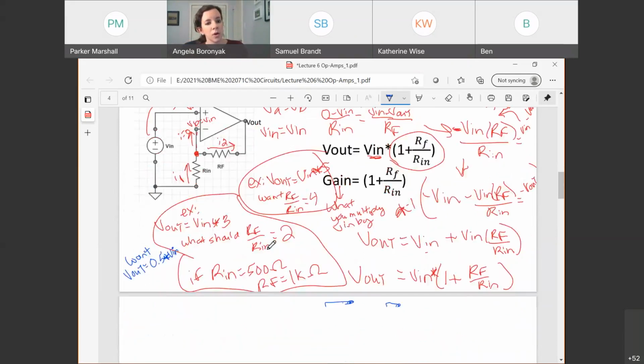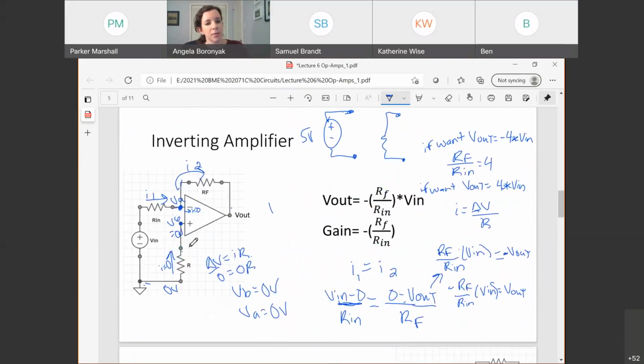We will learn, as a hint, that I can use this amplifier and put it through another one at the end, and then I flip my sign twice, and that basically multiplies by -1 once and multiplies by -1 again, in which case you can use this one to multiply by a number less than 1, but with just one of them it's always negative. So I can, if I want, have V out equal negative 0.5 times Vn.